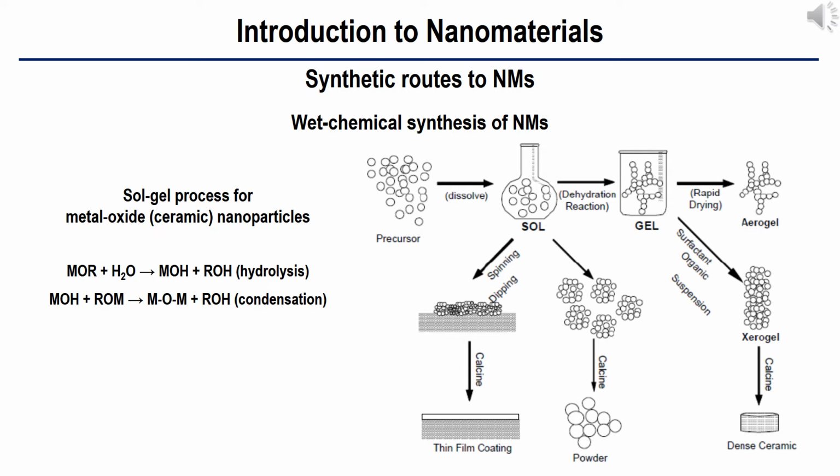The precursors for synthesizing these colloids usually consist of a metal or metalloid element surrounded by various reactive ligands. The starting material is processed to form a dispersible oxide and forms a sol in contact with water or dilute acid. Removal of the liquid from the sol yields the gel, and the sol-gel transition controls the particle size and shape.